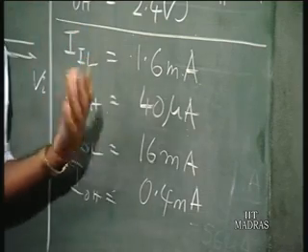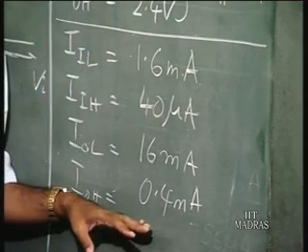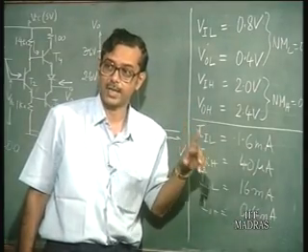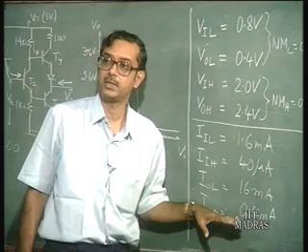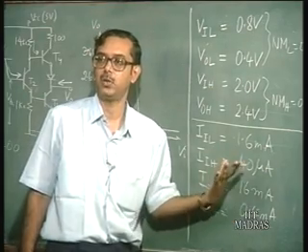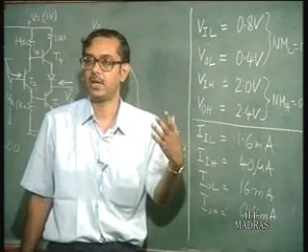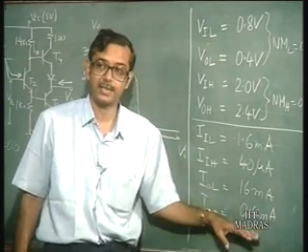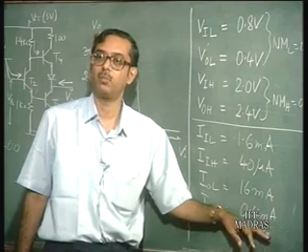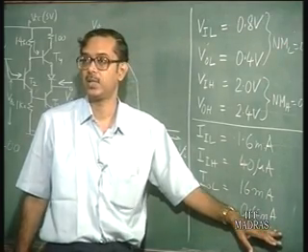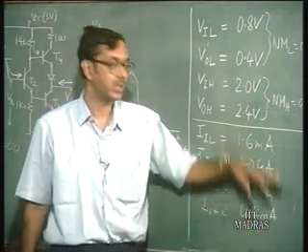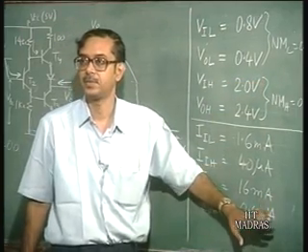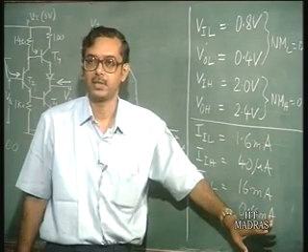That is the definition of output high, that is, the output voltage greater than VOH. So, the manufacturer guarantees that if you do not draw more than 0.4 milliamperes when the output is high, the output voltage will be retained above VOH, but if you draw more than that, it does not guarantee that the output is going to be above VOH.